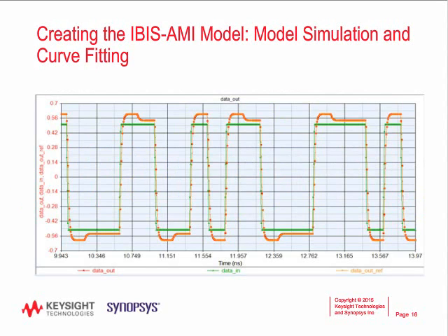This is an example of a fitted response to the TX-AMI model. The model simulation output data out is compared to the circuit simulation output data out reference for the same data input. And this measures the fidelity of the model simulation as well as your curve fitting steps during the model simulation step.